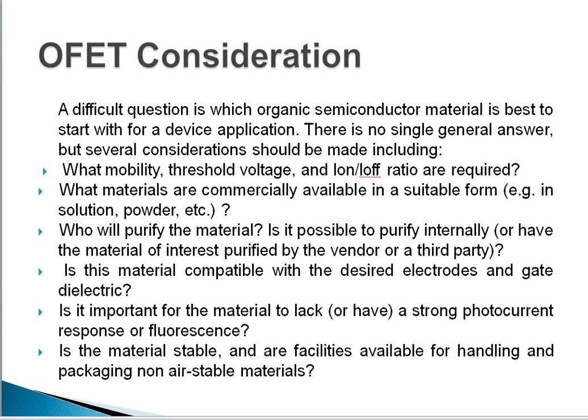Second, what materials are commercially available in a suitable form, for example in solution, powder, etc.? Who will purify the material? Is it possible to purify internally or use a third party? Is the material compatible with the desired electrodes and gate dielectric? Is it important for the material to lack a strong photocurrent response or fluorescence? Is the material stable, and is a facility available for handling and packaging non-air-stable materials?